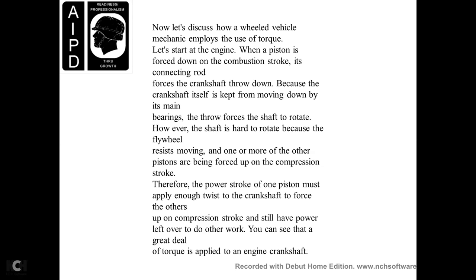However, the shaft is hard to rotate because the flywheel resists movement, as do one or more of the other pistons being forced up on the compression stroke. The power stroke of one piston is applied with enough twist to the crankshaft to force the others up on a compression stroke, and still have power left over to do the work. You can see that a great deal of torque is applied to the engine crankshaft.